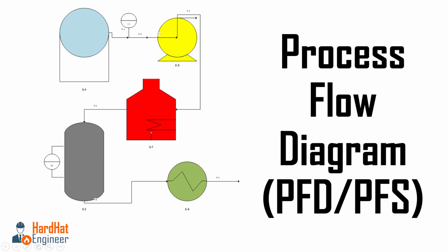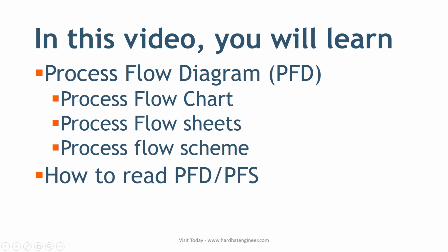In this video, you will learn about process flow diagram, which is also known as process flow chart, process flow sheets, and process flow scheme. I will explain to you how to read this PFD or PFS with the help of a real drawing. PFD is the base document that is used to develop the more complex PNID. If you want to master PNID, you must master the PFD. So please watch the video till the end.